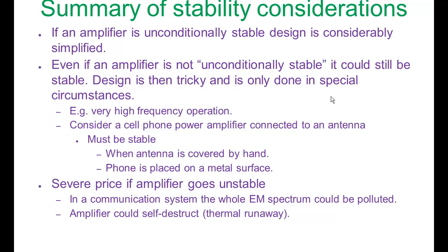Now sometimes we must design amplifiers that are not unconditionally stable. This often happens at very high frequencies. To increase our chances of being stable, high frequency design always uses Class A amplifier design. By high frequency design, I mean design at maybe 20 gigahertz and above. Consider the design of an amplifier at lower frequencies.